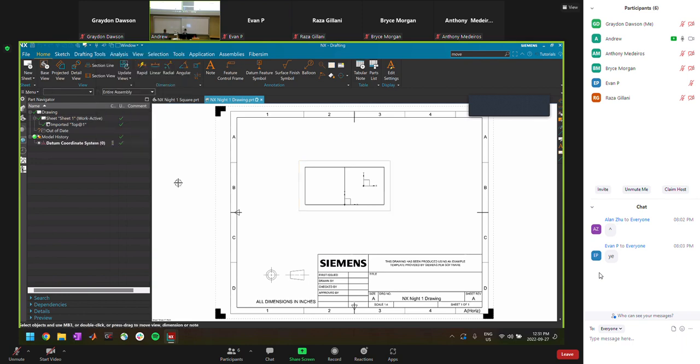Ideally, for our drawings, we'll always edit the sheet scale, just because the way that I have the template set up, which I'll show you guys in a bit, it references that scale of the sheet. If you do need to do a different scale for a specific view, you'd have to add a note under that view saying that it's at a different scale.